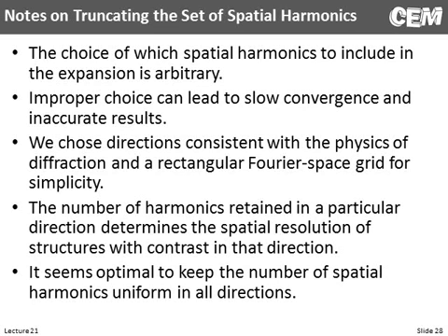We tend, and almost always, I've never seen it implemented otherwise, although we could, we choose the directions of these spatial harmonics to be consistent with the physics. So we went to diffraction theory, we looked at diffraction through periodic structures, and we can calculate the angles of those. We made our spatial harmonics consistent with that because experience has shown us that's the best thing to do. But it's not necessary. We could do it otherwise, and the code will not crash, and it will still work. Again, it may give us very slow convergence and inaccurate answers, but we are free to do it.